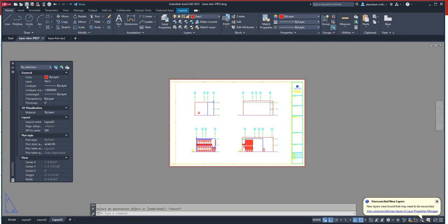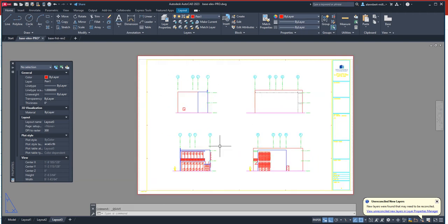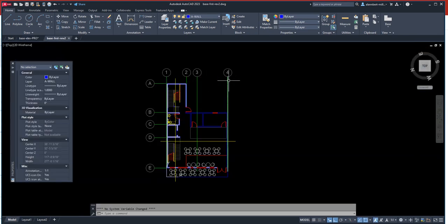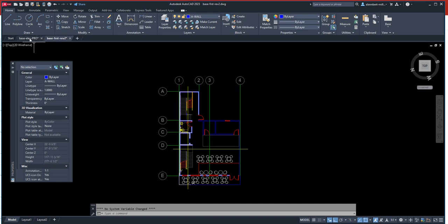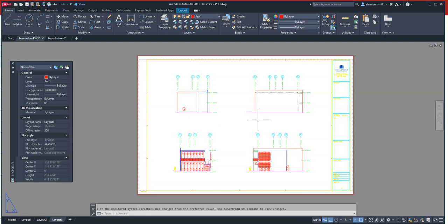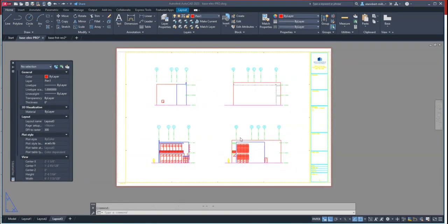Okay, save your work. And then that's how to correctly reference a grid by first doing it on your floor plan and then assigning it letters and numbers. Typically, these are 1, 2, 3, 4, and the grids that go horizontal going down are assigned letters. Okay, so next thing that we're going to do is to set a drawing title for each one of these. Now that we have added grid reference bubbles for our elevations, which is based on how we assign them in floor plans.